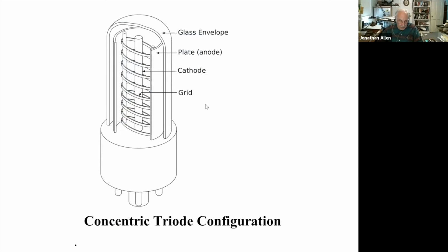They realized that the amplifier circuits for the tubes now had to have a DC path, a grid leak resistor to define the grid bias and keep it in the most linear part of the transfer curve. And fortunately, the grid leak resistor can be in megohms because the current into the grid is virtually nil.